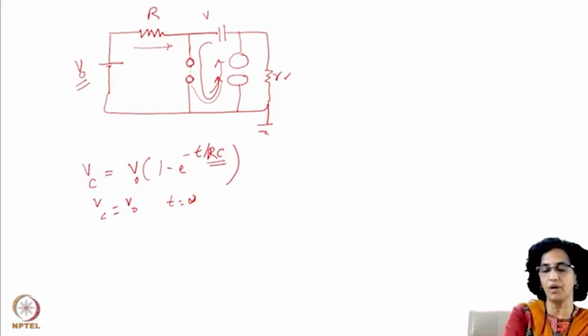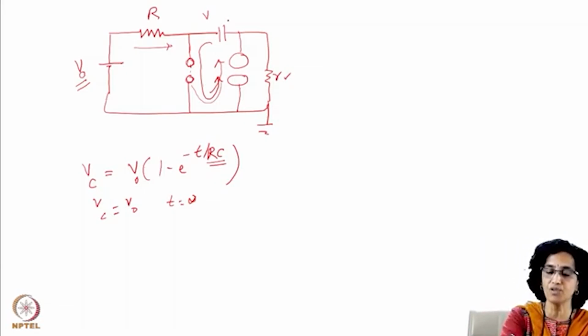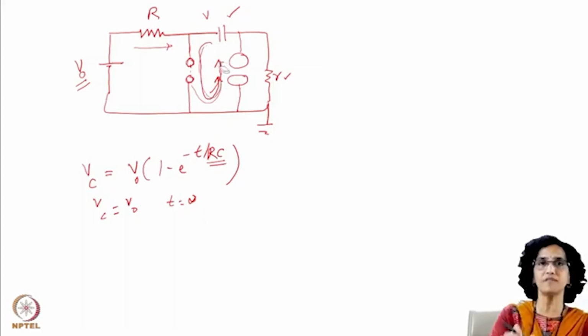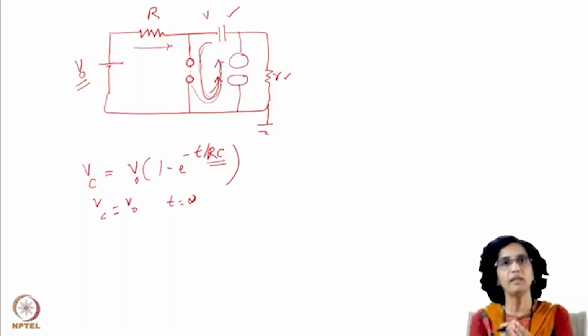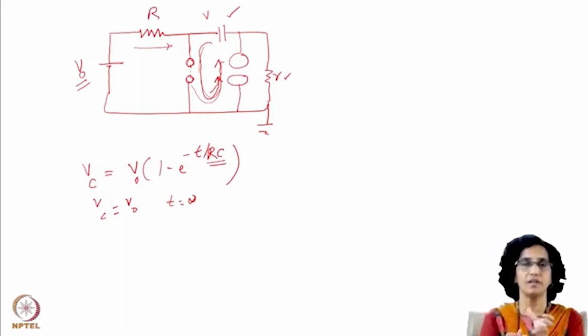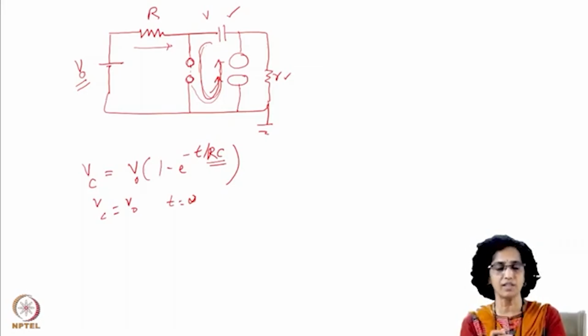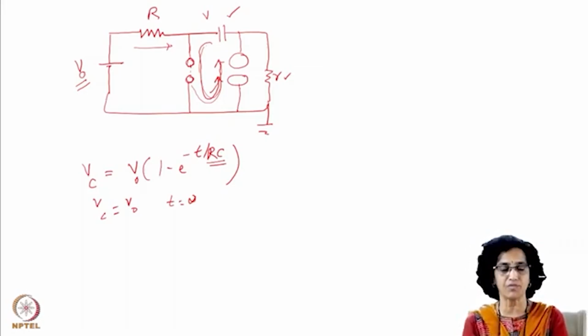And this discharge duration, on what does it depend? It depends, of course, on the value of this capacitor. It also depends on the impedance in this circuit. So the impedance of the circuit has to be properly adjusted so that your discharge duration is less than the glow to arc transition time, which is a few hundreds of nanoseconds at atmospheric pressure.